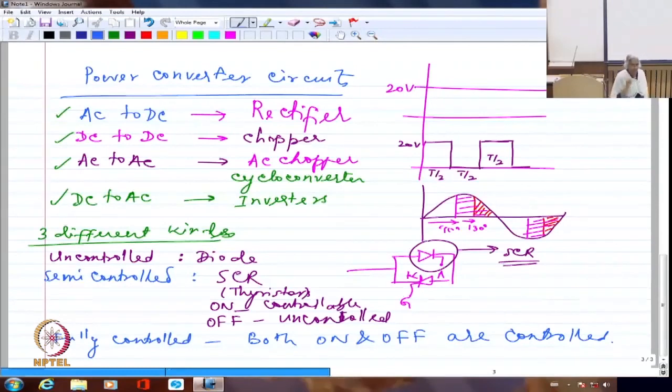So the first and foremost is to increase the voltage as well as current rating or overall power rating. The second is to make sure that the drop across the devices is minimal. How much ever we may say these devices are close to ideal, there is hardly any resistance. When a diode conducts, it's only 0.7 volts. But every 0.7 volts matters. Right?